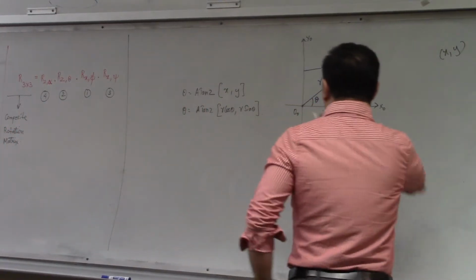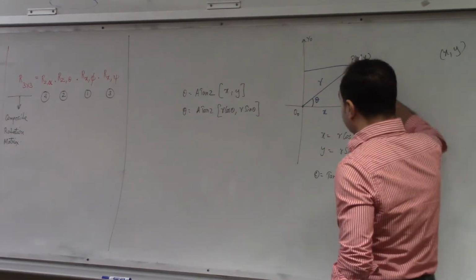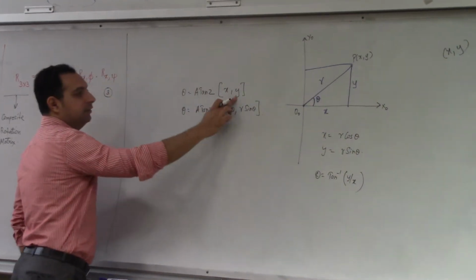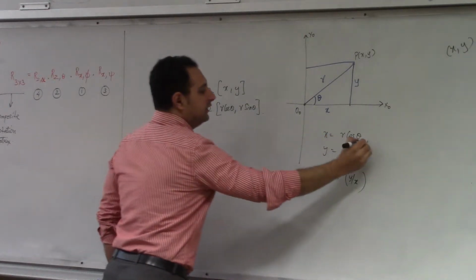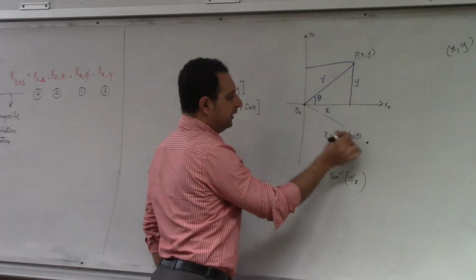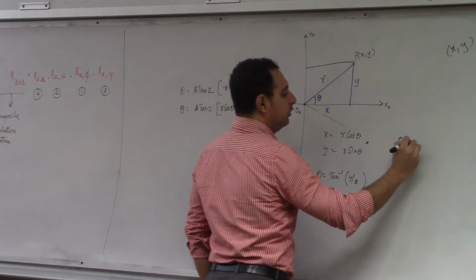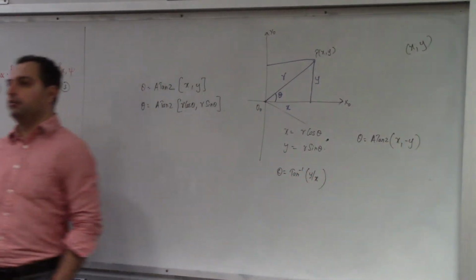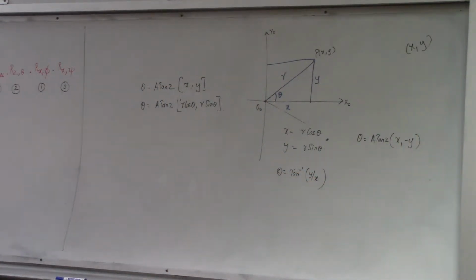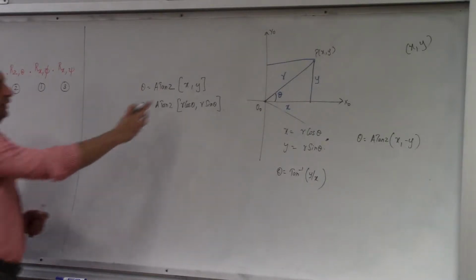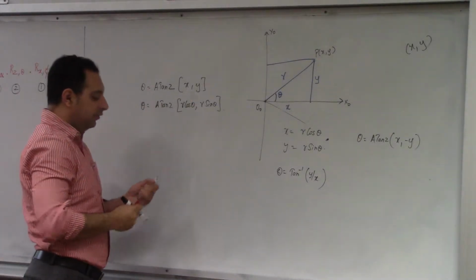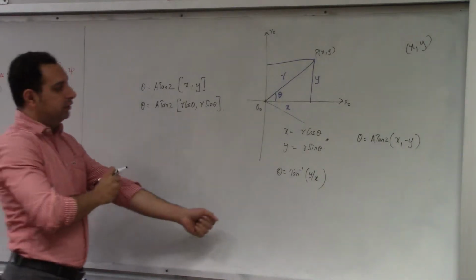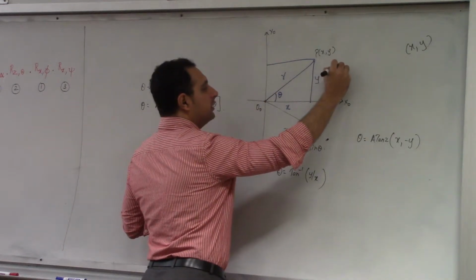The advantage is, if the point moves down, then y is negative, right? So assuming the point is here, then I'll have theta equal to atan2 of x comma minus y. So I know which quadrant of the coordinate system it is lying in, first, second, third, based on which one of these two or both are negative. For example, here both x and y are positive.